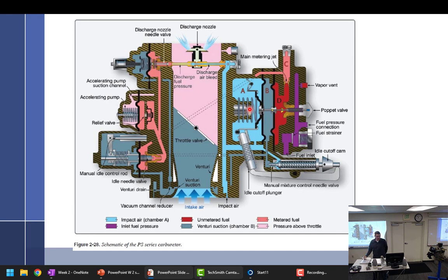What happens if we get a ruptured bellows in the automatic mixture control? It's like it's not there. It's like run rich. So it's not there. So the carburetor does what? Run rich is you increase now. Does it just run rich all the time? It runs rich when you rise in altitude, when you go up in altitude.